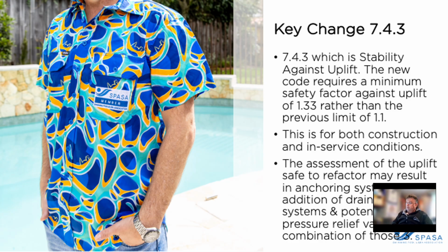Now, that will most likely result in additional weight, additional concrete that you will require to allow for. This is for both construction and in-service conditions. So, in my experience, it's the construction which will be the worst case. That is when the pool is empty, and therefore you're not having to lift just the pool shell, but the water as well. So the in-service condition won't be the worst. It will be the construction.